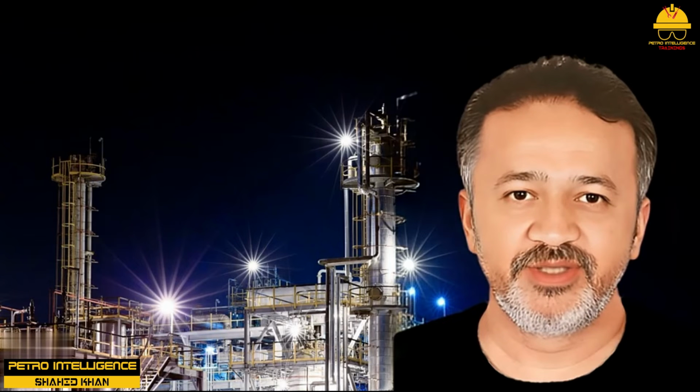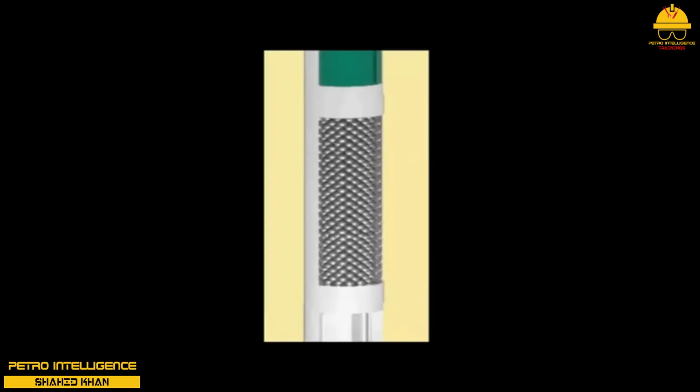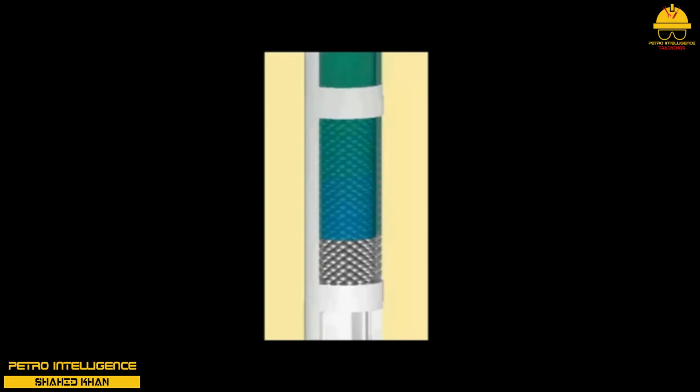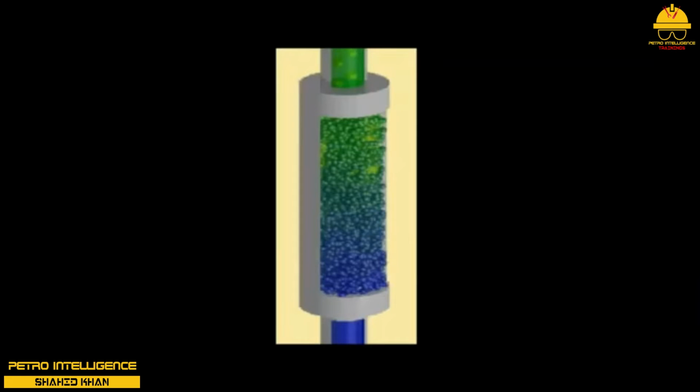Fixed bed reactors. A fixed bed reactor, often called a converter, is a vessel that contains a mass of small particles, usually 0.1 to 0.2 inch in diameter, through which the reaction mixture passes. The mass is usually a packed bed of catalyst, which promotes the reaction. The mass could also be column packing such as Raschig rings, Berl saddles, or marbles. In this case, the packing creates more heat transfer surface to give better heat distribution in the converter.